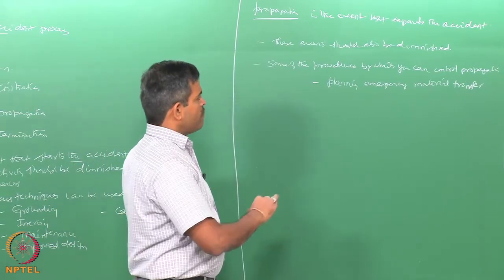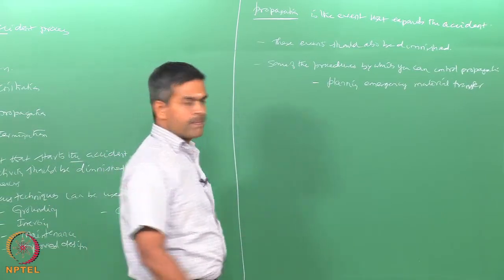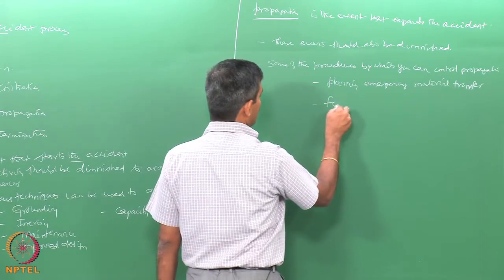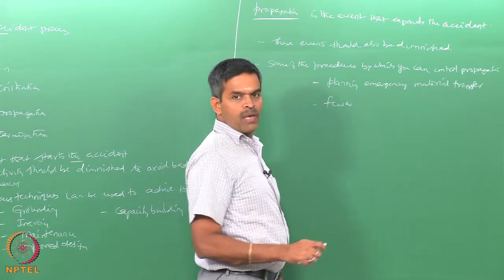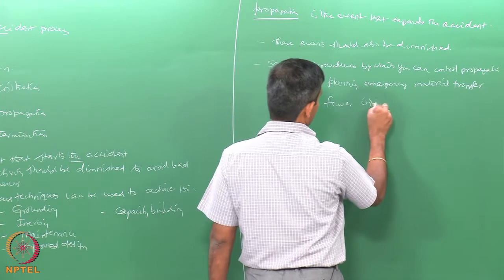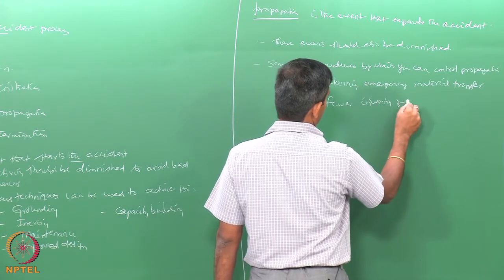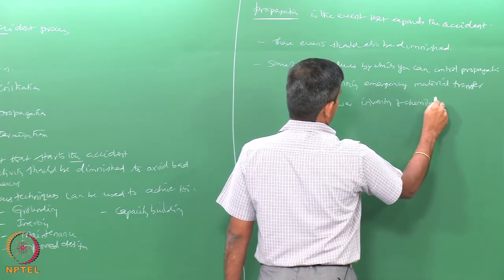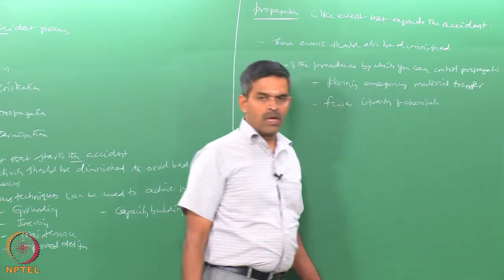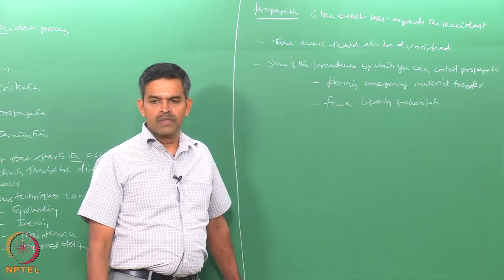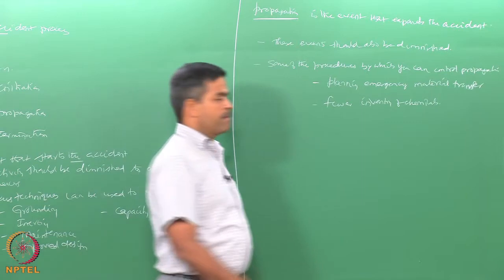So, plan for an emergency material transfer, always try to have only fewer inventory of chemicals. Do not stock large volume of chemicals in the workplace.